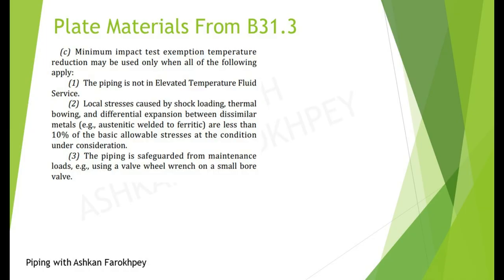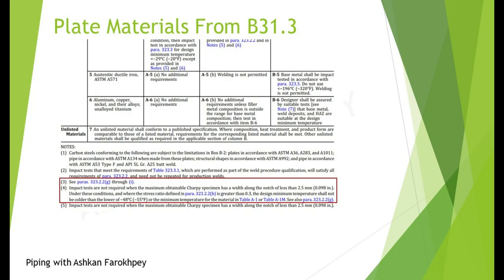Naturally, in these cases, a higher stress is applied on that material, piping or mechanical component that may cause a crack initiation or propagation. The next referred note under the table 323.2.2 was note 4. This note is talking about the limitation of Charpy test specimen dimensions, which is not our concern here. As our sheet plate has the thickness of 11 mm, we definitely can cut out the specified specimens of it according to the test procedures.